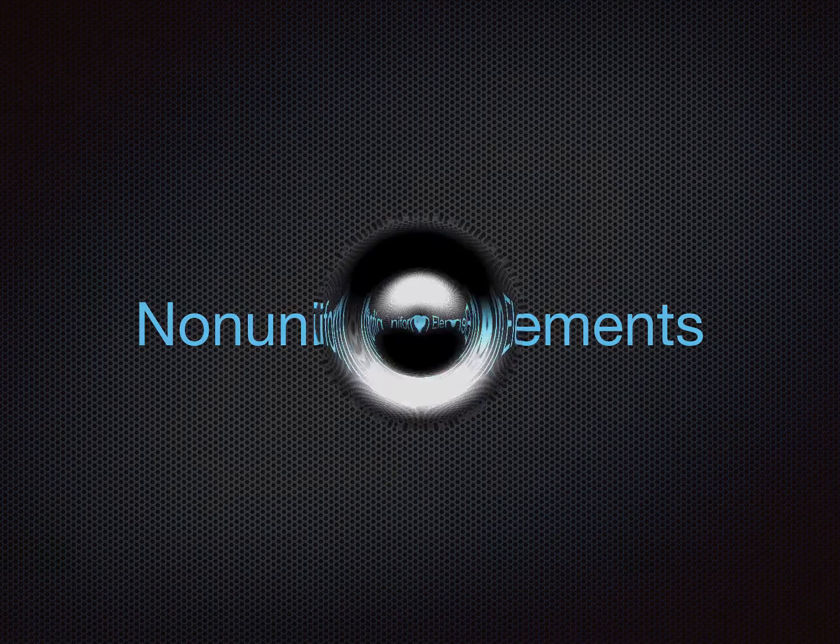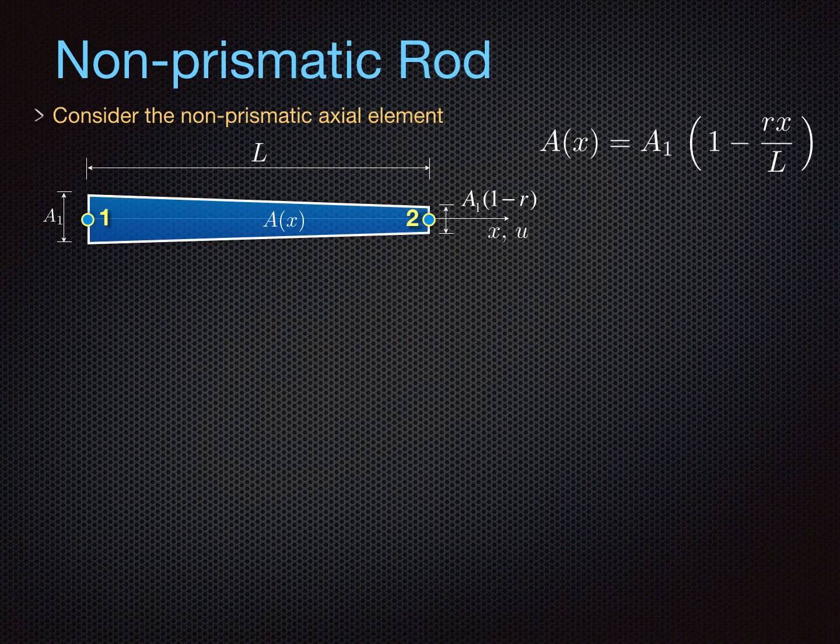Let us assume that we're looking at an axial problem involving a non-prismatic rod, such that the area of the cross section varies linearly with respect to the axial coordinate, given with some formula. For example, the formula shown on the upper right-hand corner of the slide: A sub x is equal to A1 times 1 minus r times x over L. If you evaluate this formula at x equals 0, you end up with A1, regardless of the value of r.